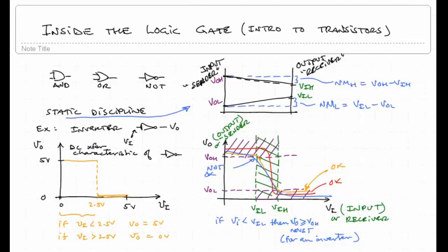And if you're going to combine logic gates together to implement logic functions that maybe you've minimized, then each of the gates used in that logical circuit must comply with the same static discipline. Otherwise, you're going to get faulty logic traveling through the circuit because there'll be different voltage references. A high coming out of one gate will not be interpreted as a high in another gate unless they're satisfying the same static discipline.